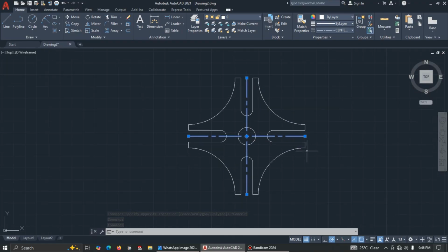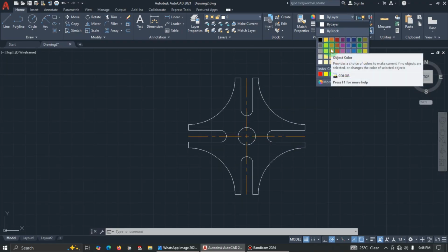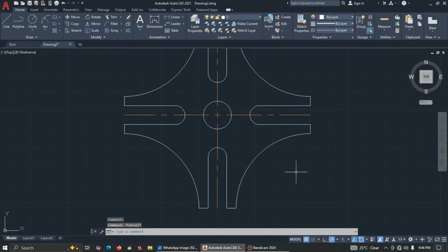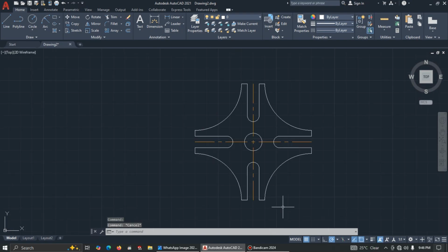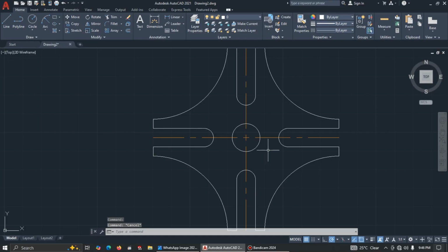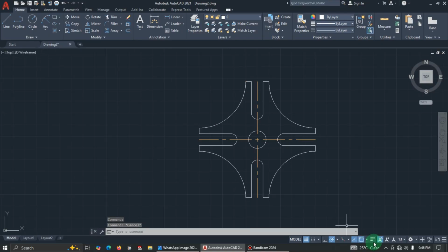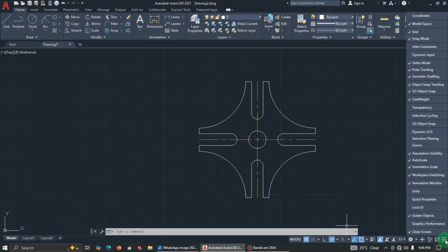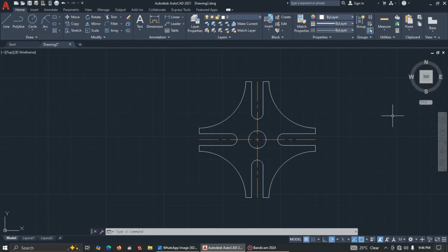Okay, so now from here we can even change the color. Let me give it this color, and that is it. Okay, so I want to increase the line width of the drawing. Now I already have my line width icon here. If you don't have it, just come to customization over here, click, and then look through. You see line width. See, mine is checked. Good.